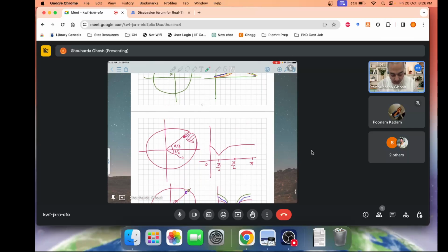Similarly, zeros will behave opposite to the poles. So a zero will pull you down. A zero will actually pull you down to 0, or try to pull you down to 0. If a zero exactly lies on the unit circle, it pulls you down to 0.